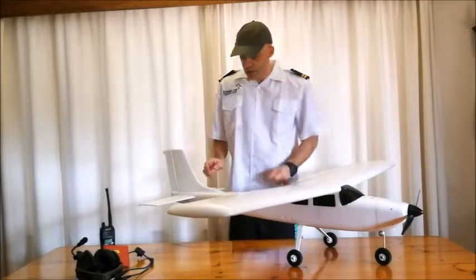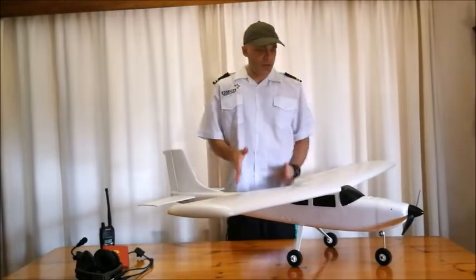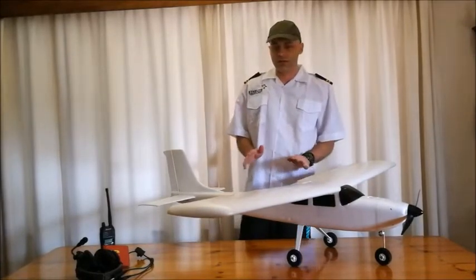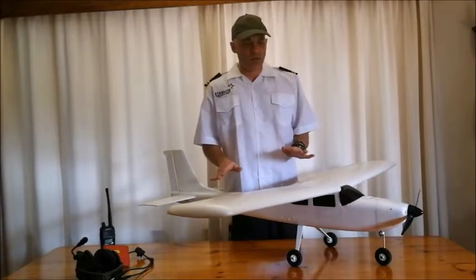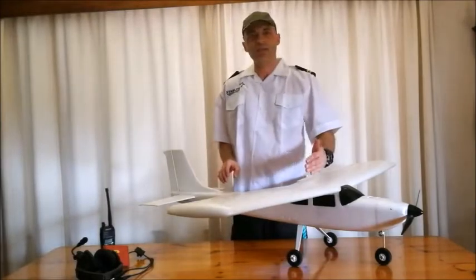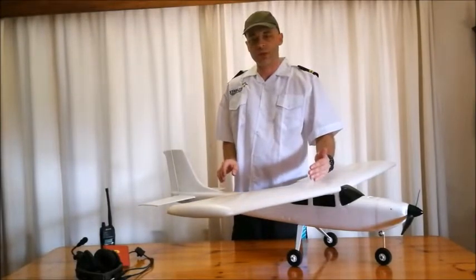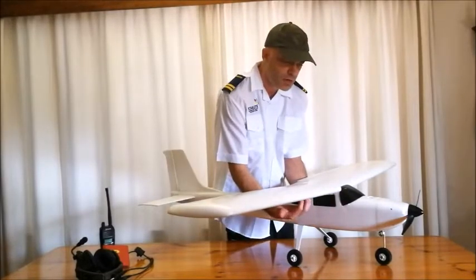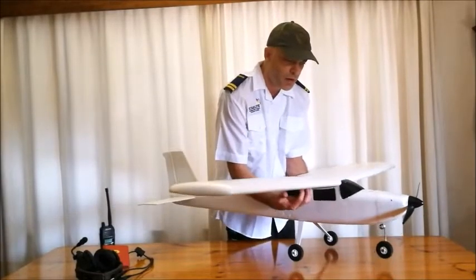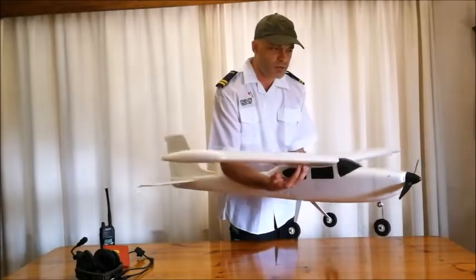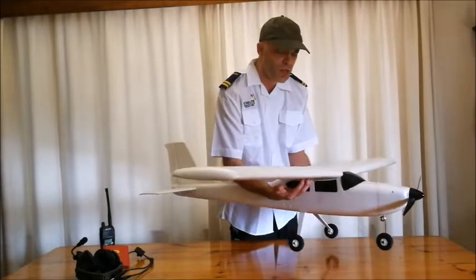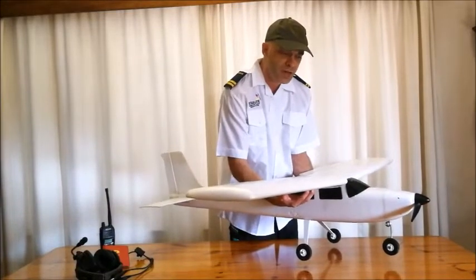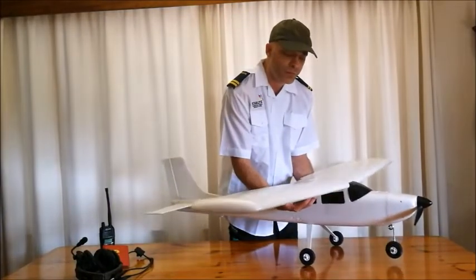Okay, so the center of gravity of such an aircraft is important, and generally it is designed to have a center of gravity at least at the center of the wings. As a matter of fact, if I take my fingers and hold here in the center of the wings and lift up, you will see that the aircraft is balanced. So it won't be tipping forwards or backwards, it is balanced underneath the wings.